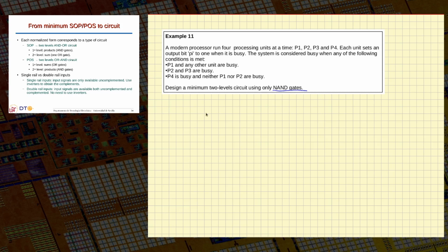So in any typical technology, an AND gate will normally be implemented by using a NAND gate followed by an inverter. So it's better to directly use NAND gates instead of AND, because each time I use an AND gate, I will in fact need two gates.